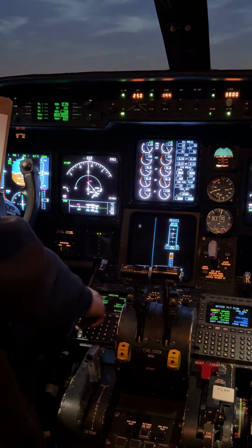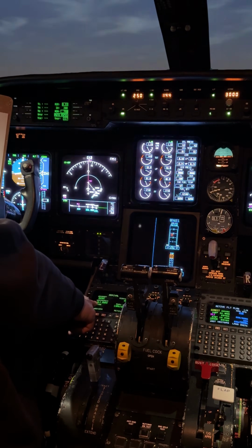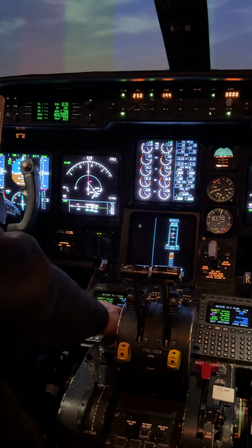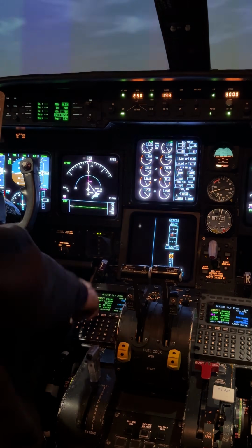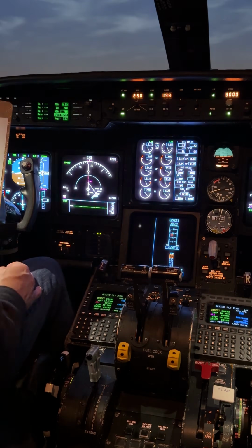So now we have Memphis, runway 36 center, RNAV to 36 center via HLI, Holly Springs for the transition, and we have LNAV VNAV. We will activate that. We're going direct to HLI. We have LNAV engaged. It's going to smart turn here in just a couple of moments.